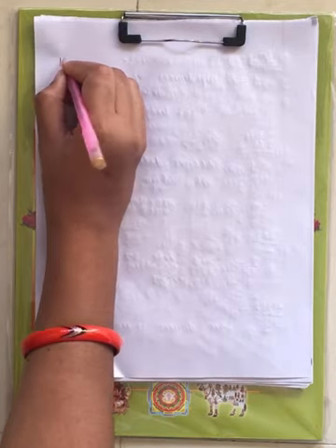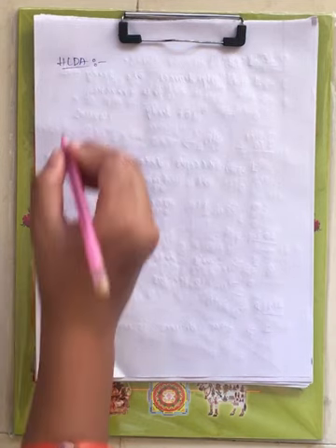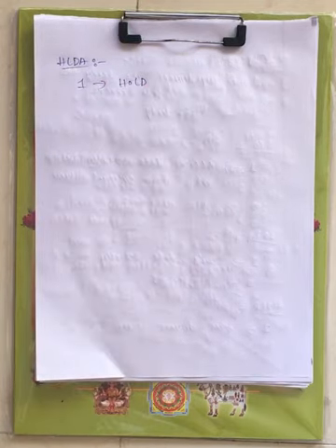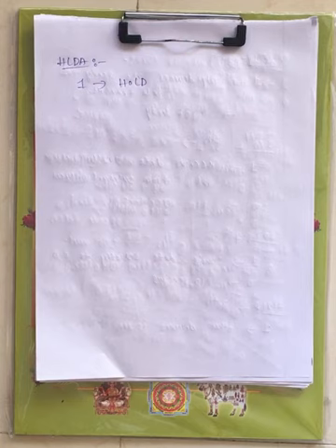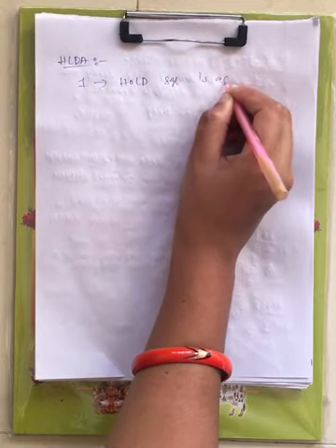Now coming to the next signal, hold acknowledgement, HLDA. What is meant by acknowledgement? Acceptance. When it is 1, the hold signal is accepted by the processor. What is meant by the hold signal? Another device is requesting for the use of the address bus and data bus. Whether to accept the hold signal or not depends on the processor, and that is given through hold acknowledgement. When it is 1, the hold signal is accepted by the processor.